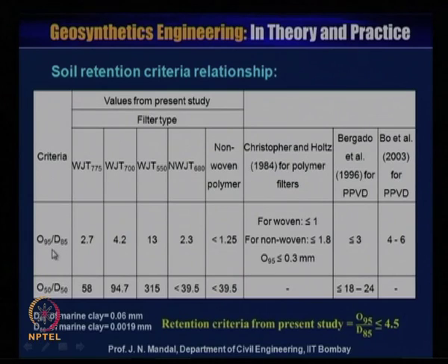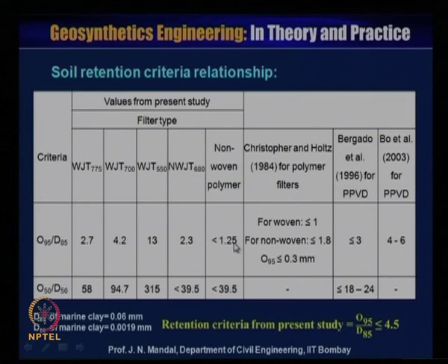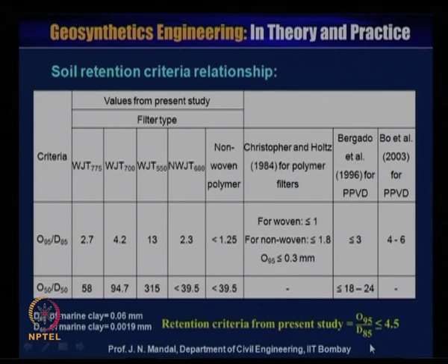So, here the D85 of marine clay is 0.06 millimeter and D50 for marine clay is 0.0019 millimeter. But what are the retention criteria for this present study? So, the retention criteria for the present study is that O95 by D85 should be less than or equal to 4.5.